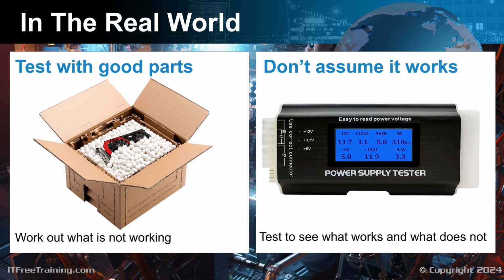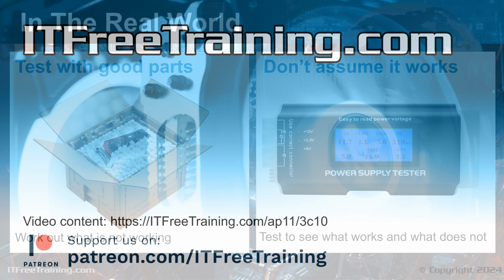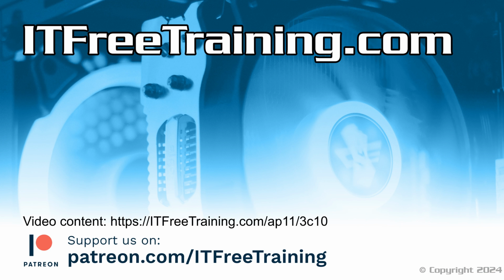There is a pin damaged on the CPU, which is causing one of the memory channels in the memory modules not to work. Thus, I can only use 2 of the memory slots on this motherboard unless I replace the CPU. This video showed a number of techniques that can be used to find what may be causing a black screen. Start with a simple, easy test and work up to the more complicated ones if you can't find the problem.